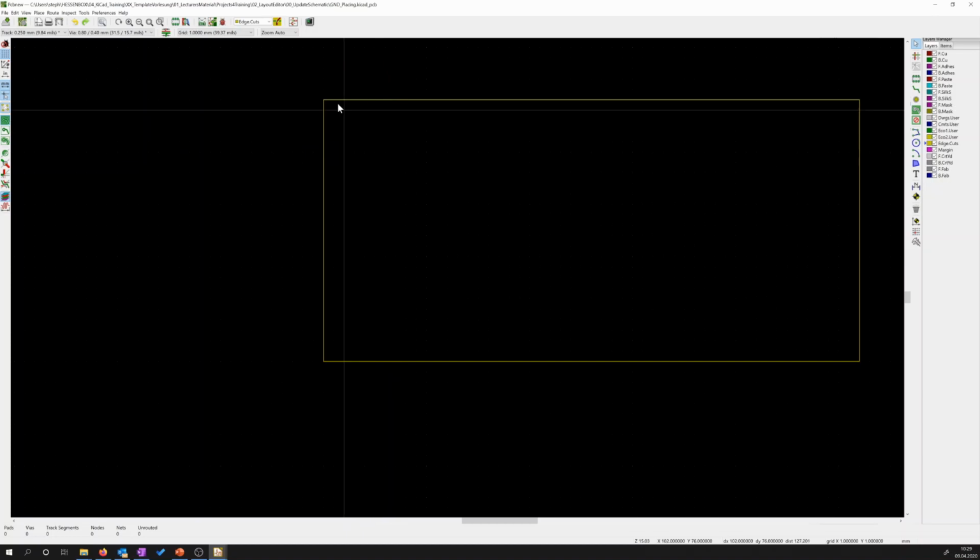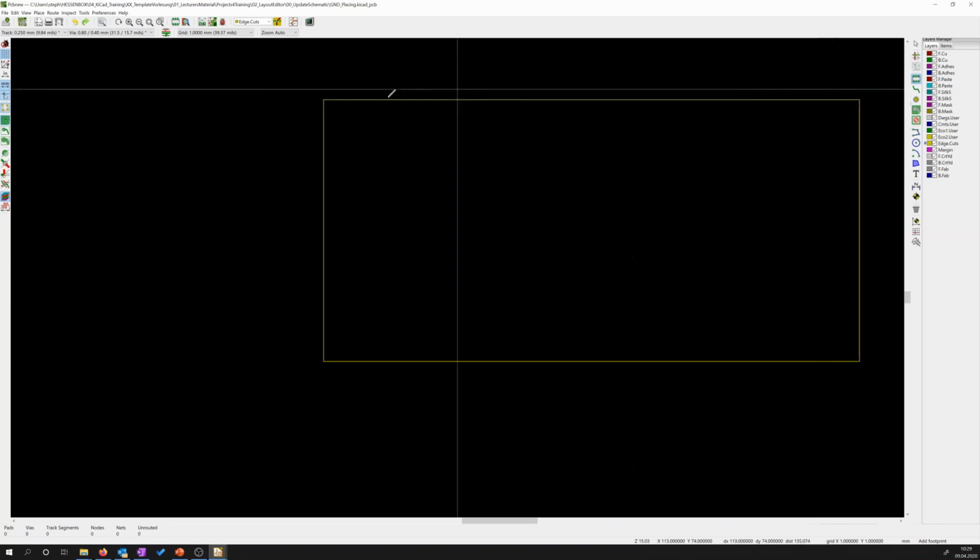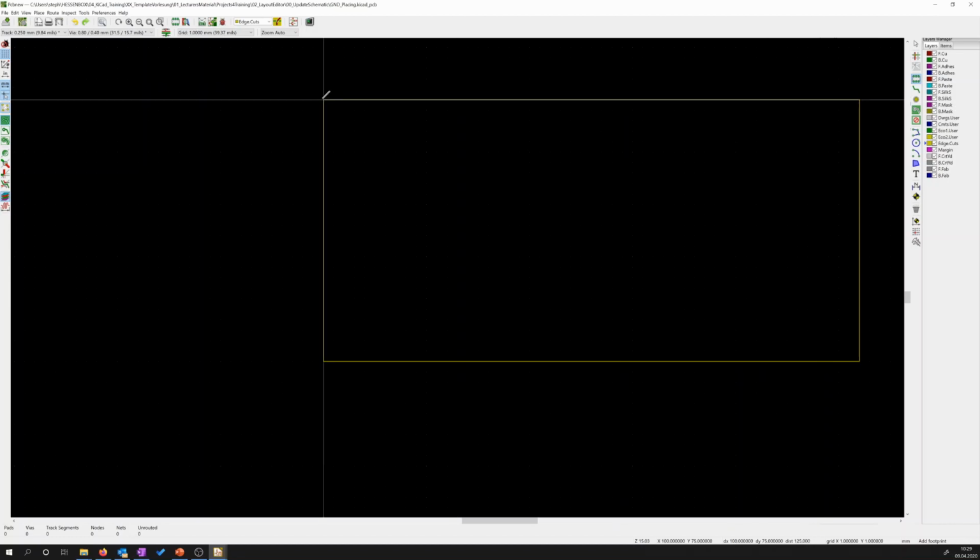To place this component correctly, we are going to select the placing components icon. Now the mouse tip changes to our pen. We want to add something, and now we use our position on the sheet. You check at the bottom and you see its X position is 100, Y position is 75.